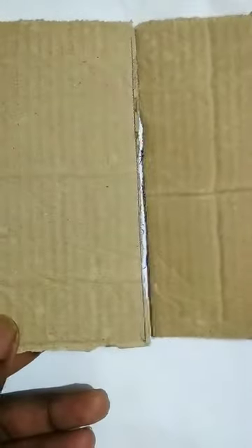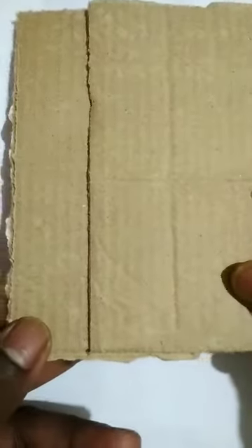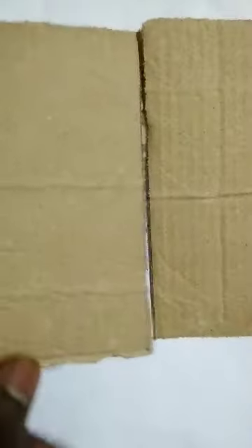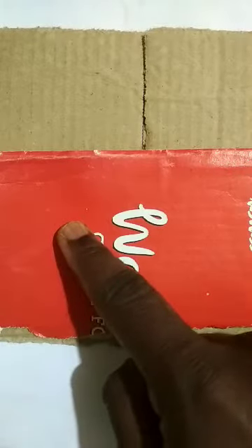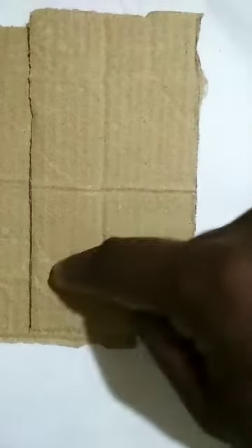Imagine you take two plates. For joining these two plates, either you can keep one over the other, which is known as overlapping, or you can keep them nearby, parallel to each other. After that, by using another plate, you can join them. Here also I am making a hole, and here also one hole. After that we can insert the rivet. In the case of overlapping, we keep one over another and, after keeping a certain distance, we make the riveting.